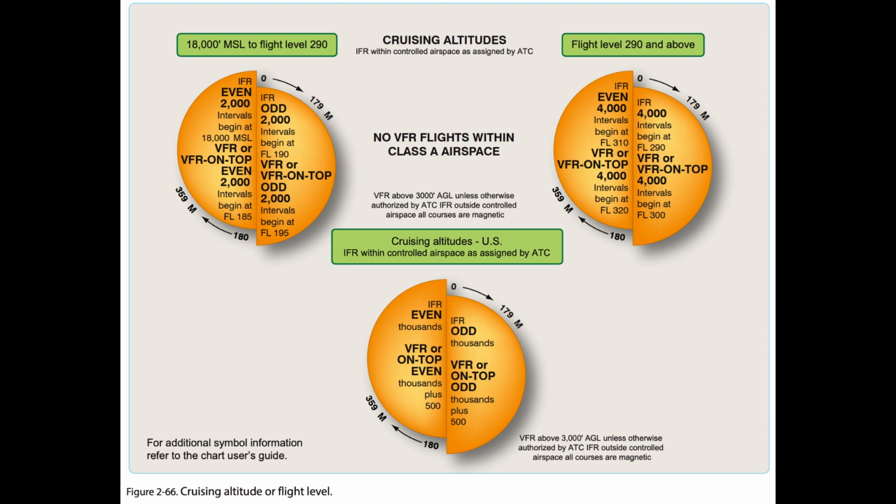When cruising below 18,000 feet MSL, the altimeter must be adjusted to the current setting, as reported by a station within 100 nm of your position. In areas where weather reporting stations are more than 100 nm from the route, the altimeter setting of a station that is closest may be used. During IFR flight, ATC advises flights periodically of the current altimeter setting, but it remains the responsibility of the pilot or flight crew to update altimeter settings in a timely manner.